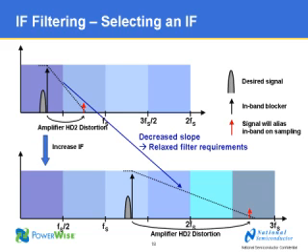So we've got our desired signal at the top of the slide, and there's this large in-band blocker. Now the amplifier in your IF filter that comes before the ADC is going to generate a second harmonic, and as you mentioned, a third harmonic. But the second is key, so we'll look at the second harmonic. In this diagram, the second harmonic is the red tone. As you can see, after we do the sampling, it's going to fold on top of our desired signal. And so we're going to need to attenuate this red signal.